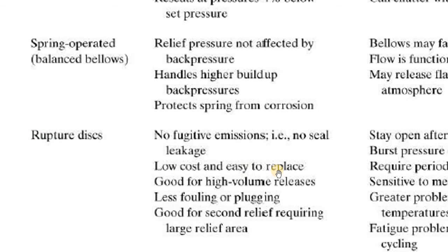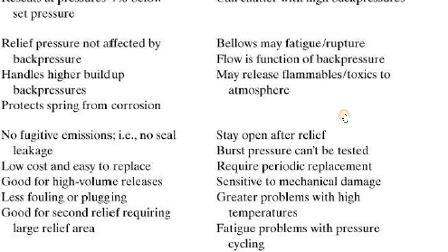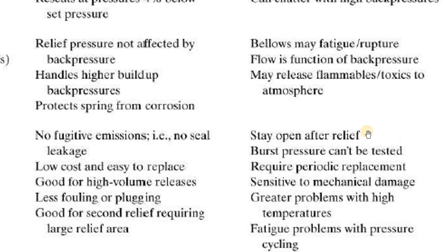Rupture discs, we already said that is low cost, easy to replace, good for high volume releases, less fouling, it's always good, right? No seal leakage, but what? Stays open after relief. That is the main problem. It stays open after relief. But it was designed to do this, okay? So we're just mentioning that this is a disadvantage so that we can take care of that disadvantage by another relief valve or safety valve. Okay, and of course we have some fatigue problems if it opens, but it does not break. It's not really opening. It's just moving up and down, up and down, and so on.